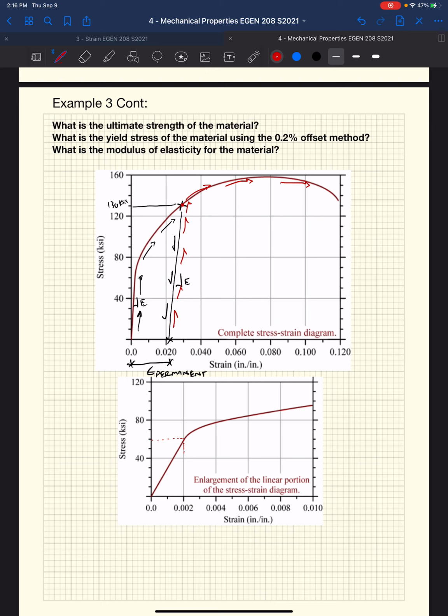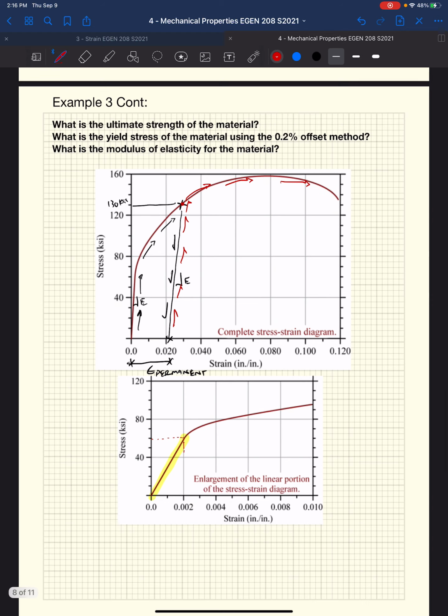They absorb, and so they want to essentially stay elastic. So we want them to stay in this linear elastic region. We don't want to permanently deform them. We don't want to go over a bump and then all of a sudden that spring gets half an inch shorter. Then we go over another big bump and it gets another half inch shorter. Pretty soon we have no suspension at all. So we want it to constantly travel along this linear elastic region.